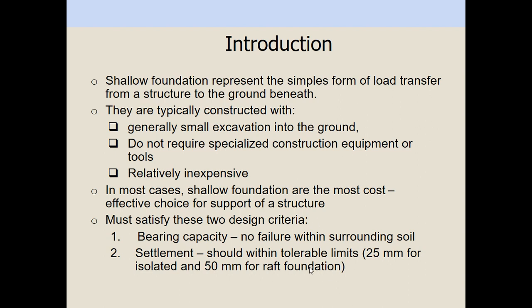And then of course you have to check the settlement, and the settlement should be within the tolerable limits. For example here, this is only an example, the maximum settlement is only 25 millimeters, 2.5 centimeters, for isolated foundation or pad foundation, and 50 millimeters for raft foundation or mat foundation.